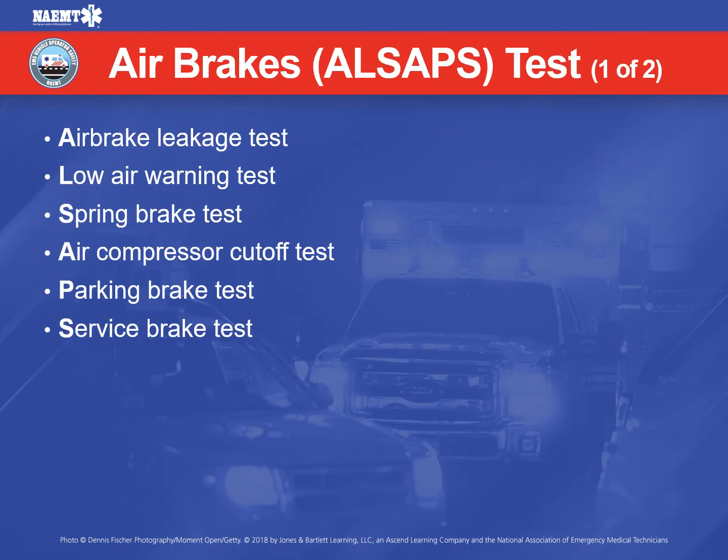Air brakes should be tested daily by performing the ALSAPS method, which is the air brake leakage test, the low air warning test, the spring brake test, the air compressor cutoff test, the parking brake test, and the service brake test. If the vehicle has air brakes, it's important to perform these tests at the beginning of every shift. If your service has vehicles with air brakes, learn how to properly do these simple tests.